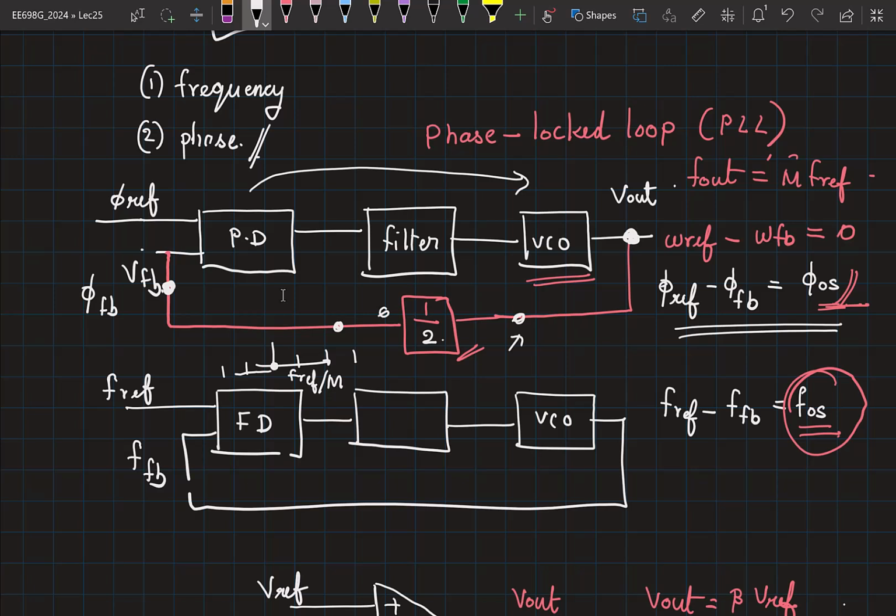So you can have some particular frequency profile here, some profile here. What finally matters is what VC is seen by the VCO, because the VCO is the one that is giving you the frequency. So a lot of design considerations go into how you design the divider, how you will switch between the integer values of division, etc. But it is possible to get a fractional multiplication at the output.